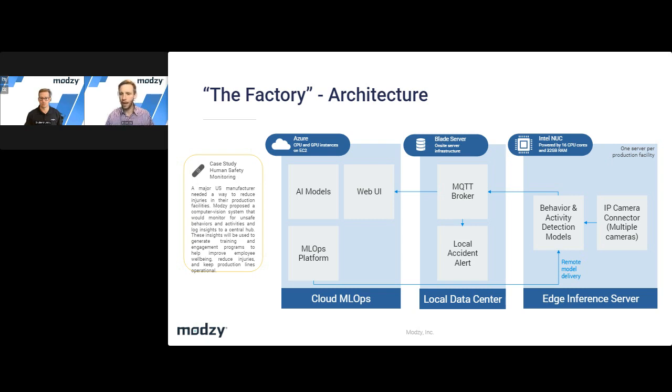In the case of IIoT, industrial manufacturing environments, MQTT has a lot of benefits, and it means you can really reduce the amount of noise moving across the wire. In this case, the MQTT broker really only hears if an issue has been detected. We don't have to pass all of the raw video data. We don't have to pass all of the model outputs to that broker for other systems to subscribe to that information. We can only send information about detected accidents and issues, or detected maybe poor form or improper technique considerations that would then be logged for future review.